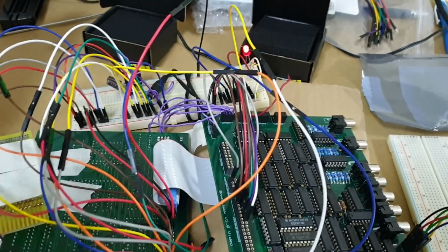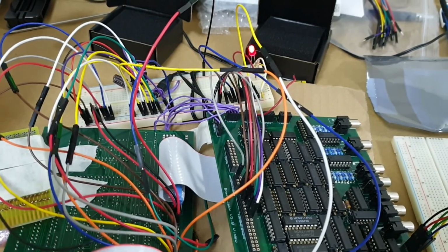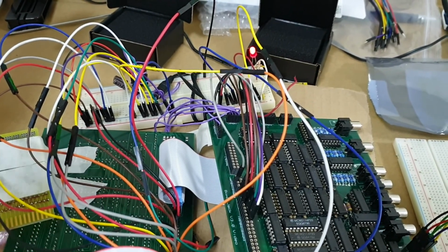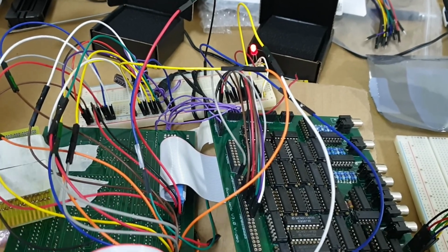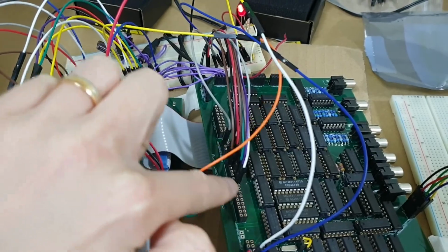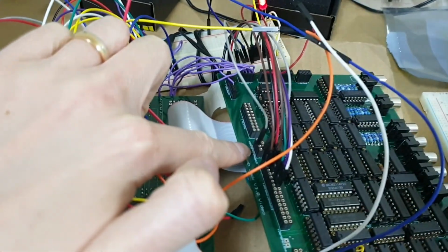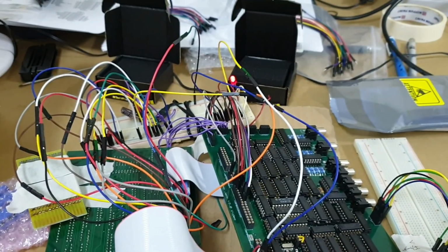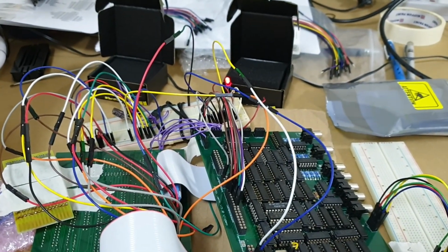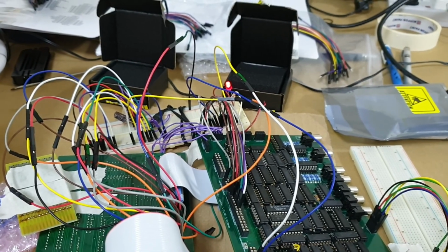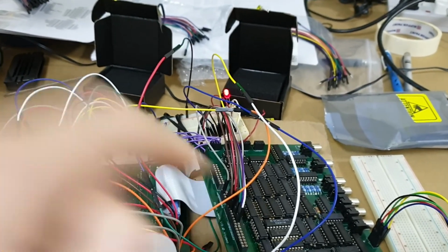So it's going to be a very non-optimal, very slow 24-bit data bus with 8 bits of data, and that's just going to flow straight into here, into this header, into the extended memory bus header here, and that will enable me to control in a very, very slow way by poking output 8 bits from the Commodore 64 user port into here.